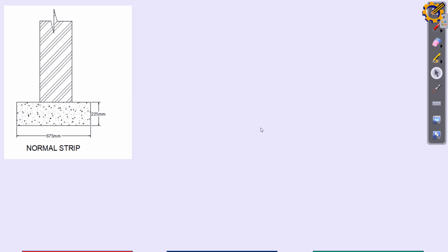When they say something is precast and something is cast-in-place: precast is when I create the NEPA pole on the floor, convey it to the construction site, and drive it with a hydraulic hammer into the ground. In precast, those areas where the concrete did not reach, or where there is a defect, I can actually see because the piles are on the ground. But cast-in-place is when I go to the construction site, excavate the soil, pour concrete into it, then put the reinforcement inside. So I can't see anything on the inside. I can only assume that all is well.